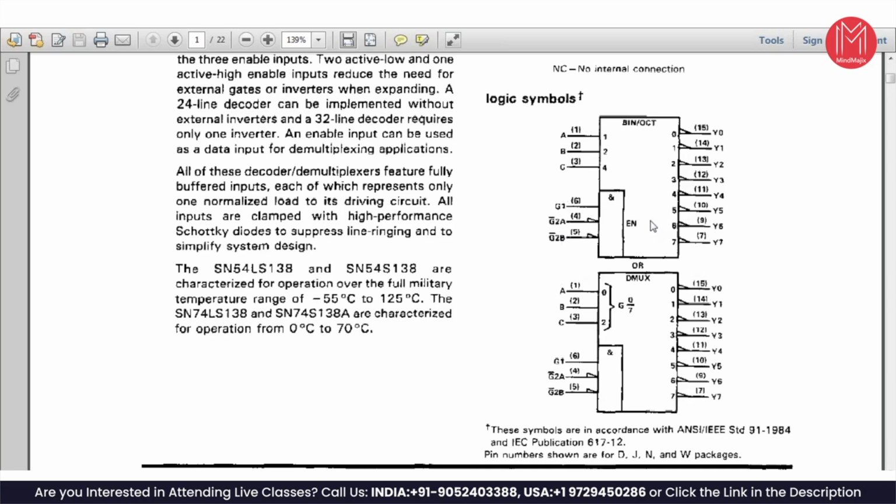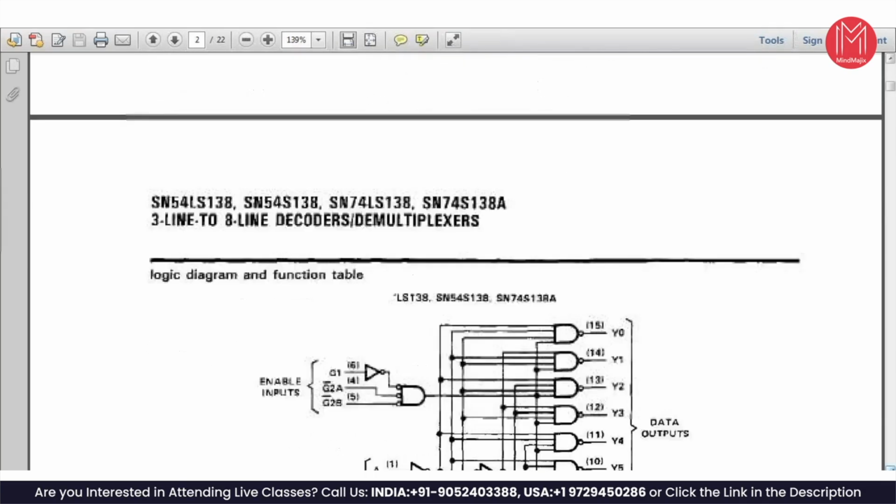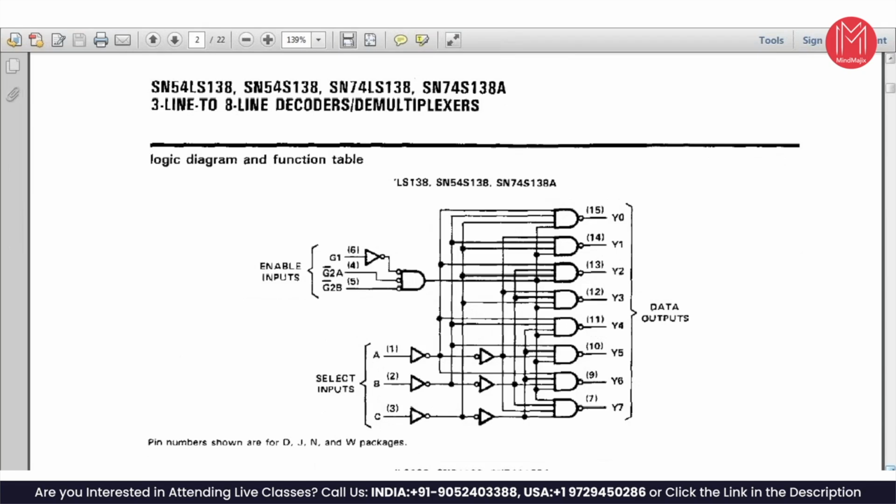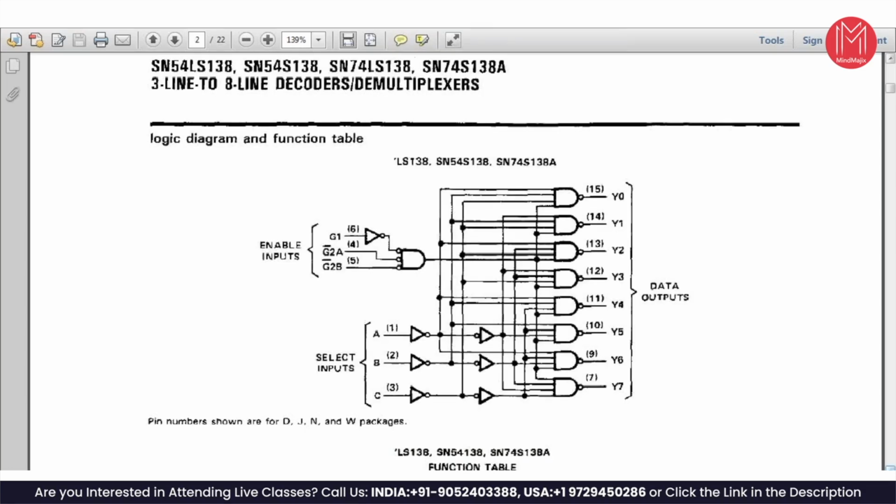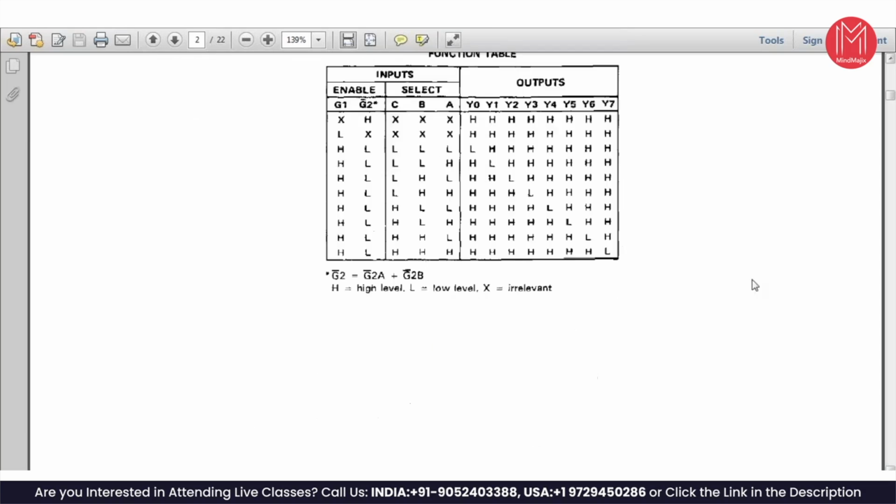We'll look at the truth table in a while. But essentially, this decoder is decoding the value passed in onto one of these 8 lines. That's a decoder. Typically it was used in the olden days for memory decoding, but these days it's done in software. So here are the enables G1, G2A and G2B, and let's look at the truth table.